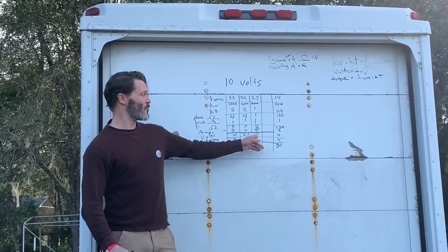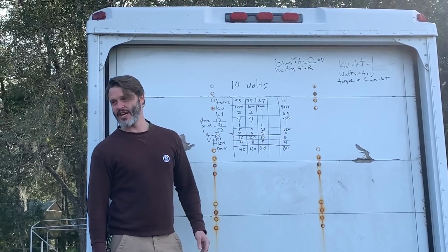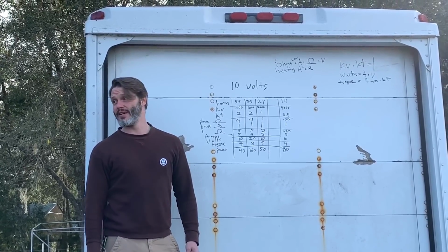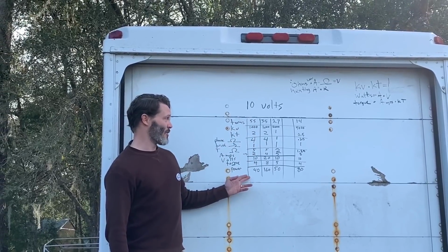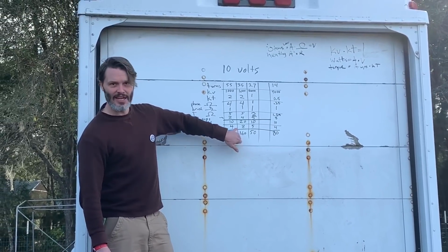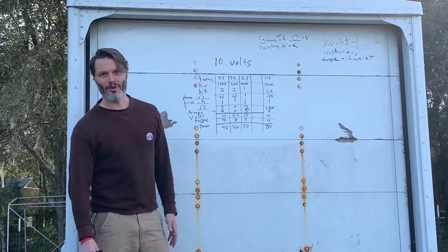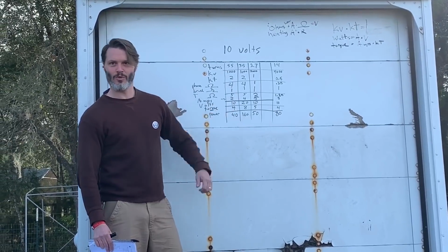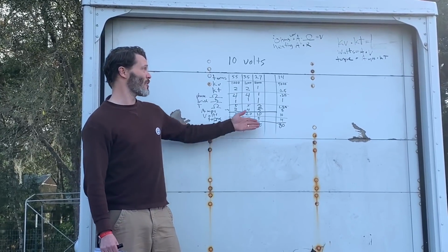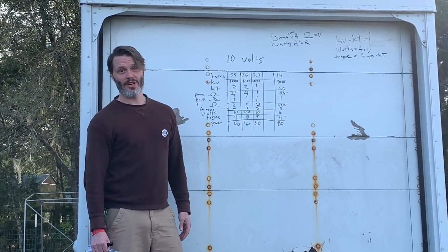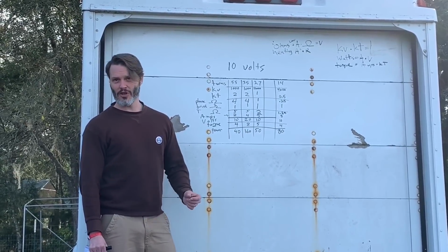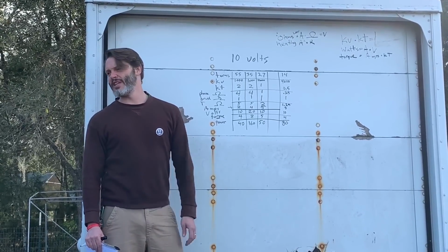And until you get too fast and you start saturating the brushes in this case, they're all essentially going to make the same amount of torque as long as you're spinning them the same speed. So that is why the 55 turn motor on twice the voltage is essentially, well, in this case it's actually beating in torque. But again, if we doubled our voltage on the 27 turn, we'd even the playing field, and the 27 would be even more powerful. So a really long-winded way to say, hey, for brush motors, we can tell that maybe the racers knew what they were talking about. That 27 turn, or something similar in speed, like a 13 turn, a 5 slot, a Crawlmaster, that's our golden zone of torque.